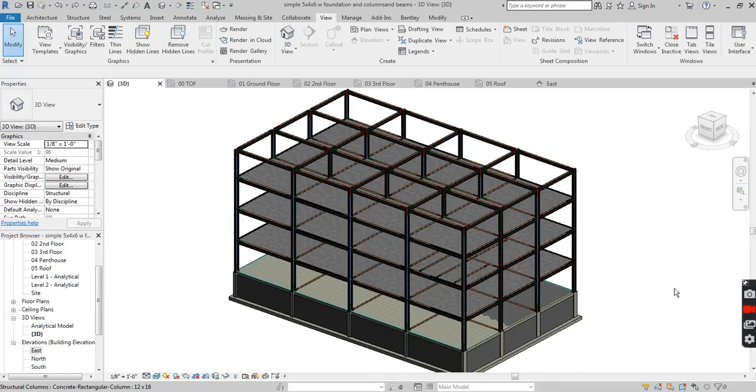Hello. In this video, we're going to show how to put trusses on a building. So here's an elongated building. It's a 4x3 pattern, and the east-west dimension is definitely longer than the north-south dimension. It is more typical to place trusses, particularly slanted trusses or scissor trusses, in the shorter direction. So we can do this in a number of ways.